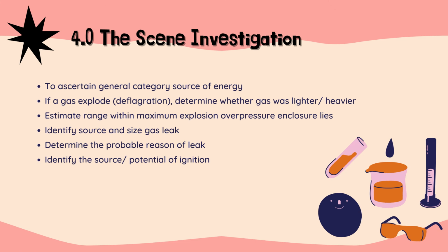The scene investigation. The purpose of the scene investigation is to ascertain the general category of the source of energy. If it is a gas explosion, determine whether the gas was lighter or heavier than air. Estimate the range within which the maximum explosion overpressure lies. Identify the source and size of the gas leak. Determine the probable reason for the leak and identify the source or potential of ignition.